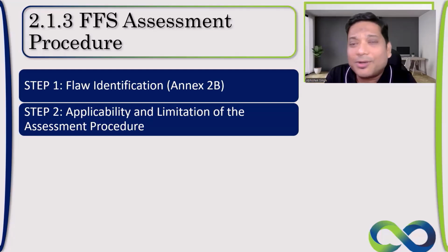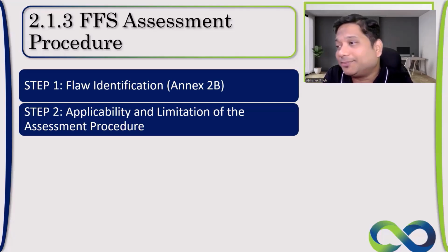What will be the difference because of that? Whether the equipment which you are going to analyze was designed as per code or standard or not, does it make any difference on the assessments? Calculation will be based on code. If I make one statement that the equipment was not designed as per code, can I perform fitness for service? The answer is yes, we can do.